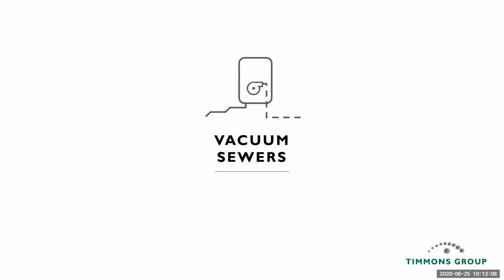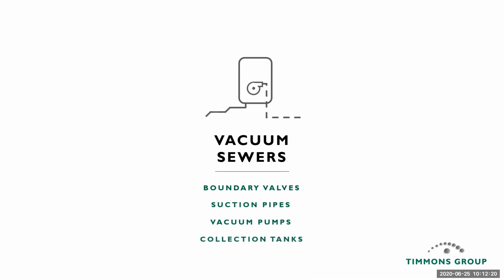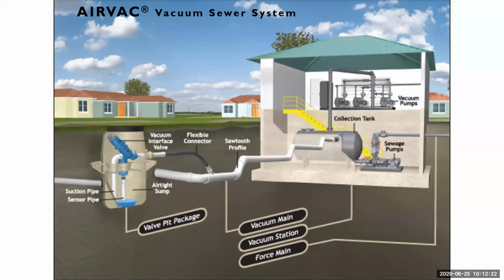And then I also want to mention vacuum sewers. Typically, you'll see vacuum sewers in coastal plains or very, very flat areas. For vacuum sewers, you've got boundary valves, suction pipes, vacuum pumps, and then the collection tanks. So for this entire presentation, this is the only non-Timmons Group image. Everything else is either Timmons Group design or project photo, but I borrowed this from AirVac. They make vacuum sewer systems, and this was just a great, simple overview of what a vacuum system consists of.